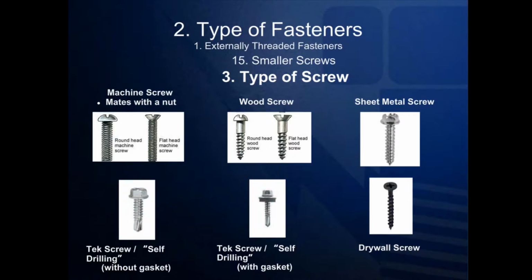Although both sheet metal screws and tek screws are designed to drill into metal, tek screws are often mated with rubber neoprene washers, which allow them to hold roofing and metal siding onto metal buildings. These screws come in a rainbow of different colors, and since it is paired with the neoprene washer, it creates a leak-proof seal, thereby preventing leaks when it rains.